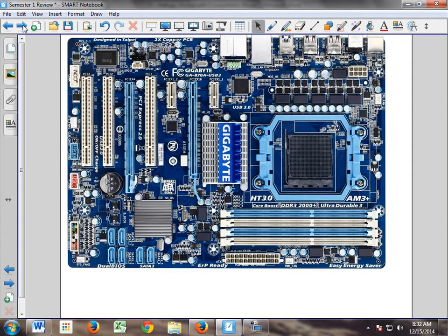And you might want to look over the old one. I think this actually is a picture I used in the test. What CPU manufacturer is this for? AMD. How can I tell? It has holes and it has no hook. Okay, if it's got holes, it means it is a PGA socket, for pin grid array. It's also a ZIF socket is the other way to call this one. And there's my Northbridge. There's my Southbridge. How many video cards can I put in here?